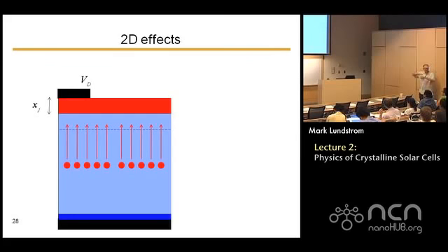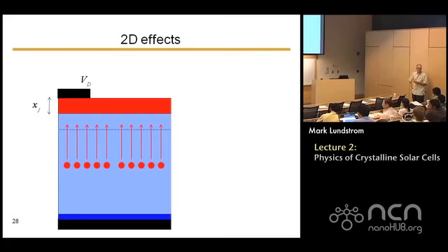There's a metal grid of fingers on the top contact. This is repeated over here. So I can illuminate maybe 90% of the area. My metal grid obscures 10% or less of the area. So what happens is that when my minority carrier electrons are generated in the base, they diffuse towards the p-n junction and are collected. Once they get collected, they have to travel laterally out the contact. And as I go towards the contact, the magnitude of that current just builds up because I just add all of them that are collected along that contact.